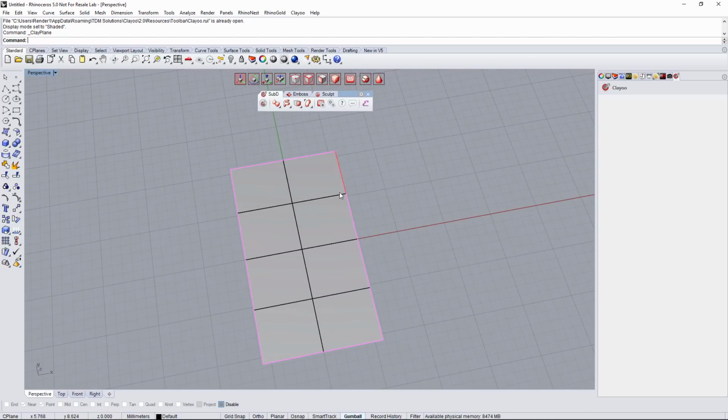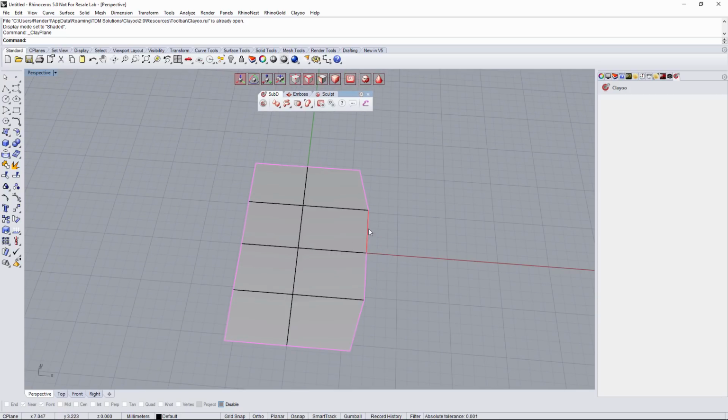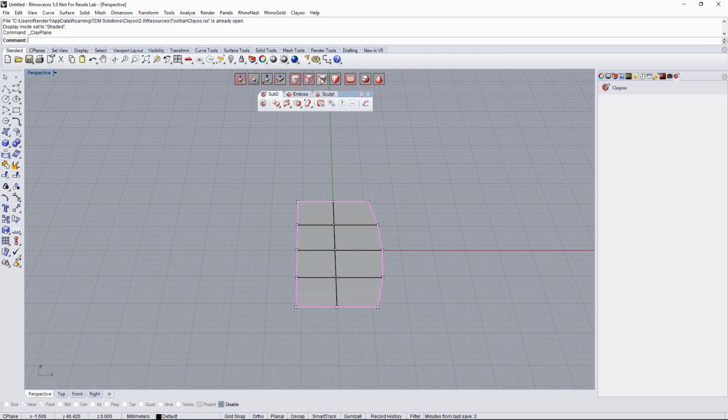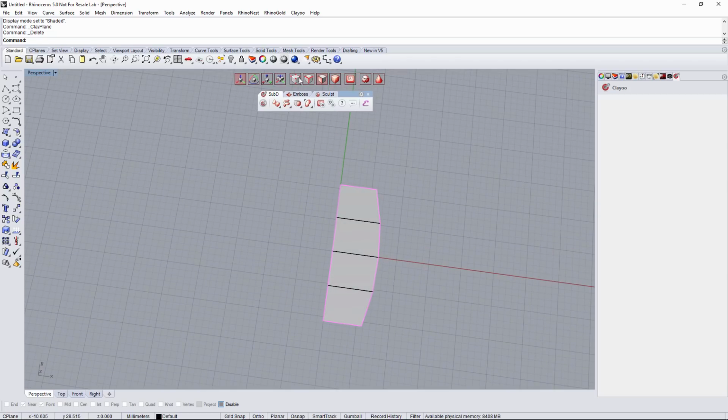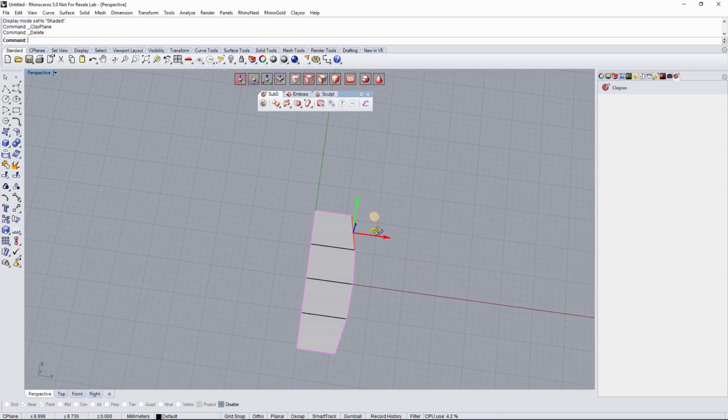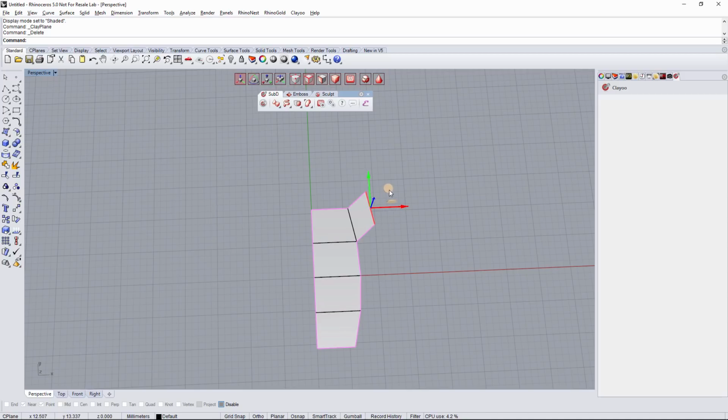So from here I'm gonna start just changing a little bit the geometry. I'll just make sure that one side is the one that I'm working on, because I'll get rid of the other one. So I'll grab these faces and delete them, and I'll grab this edge in here, and holding Alt on my keyboard I'm gonna drag it, and I'll do the same also in here, and I will scale a little bit the shape in here, and I can refine the shape in there.